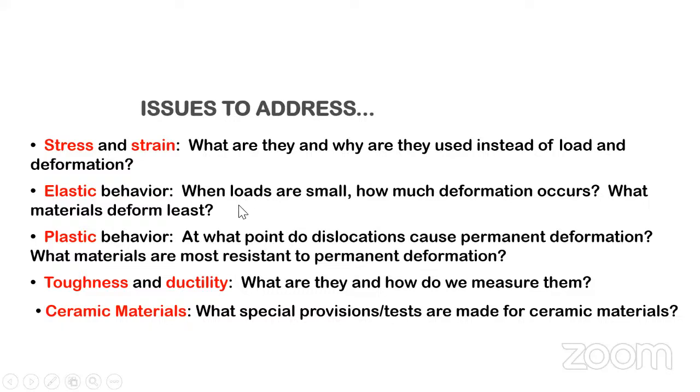Whatever forces are applied on your material, or whatever different kinds of force action take place on it, we can study using this test. The parameters we can study using the tensile test for polymeric materials are stress and strain, meaning the deformation of the polymeric material when applying a specific stress or force on it.